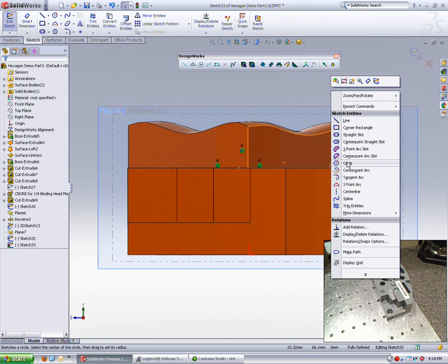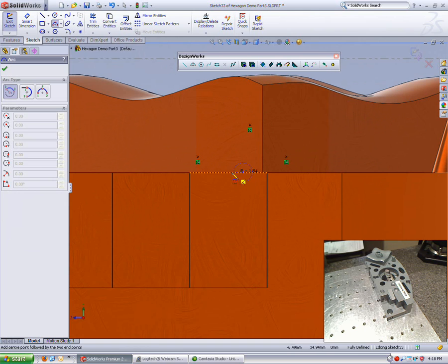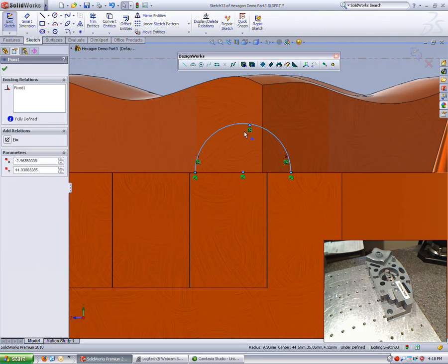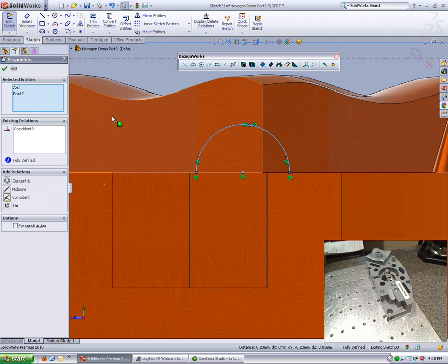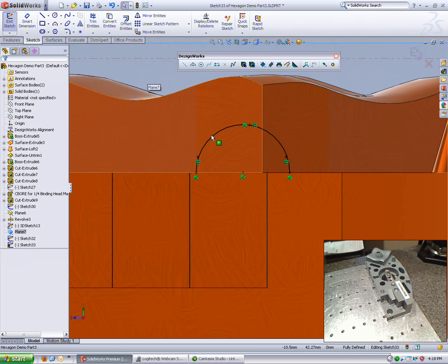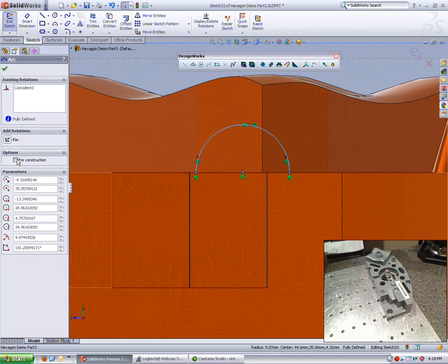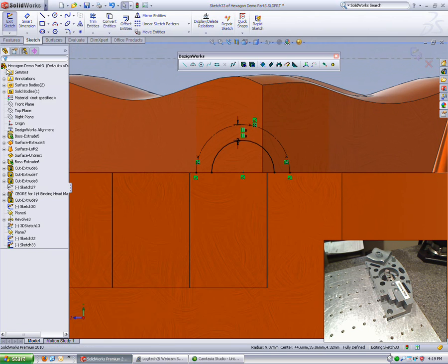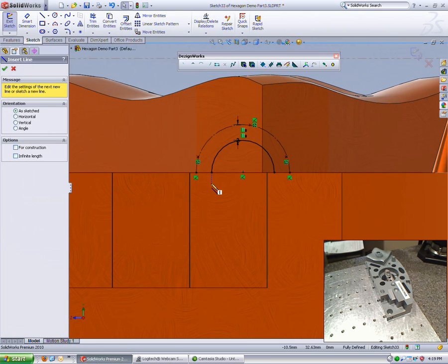Again, we may want to offset the arcs that are going to be created so that we get an accurate offset from our ball size. So here we're going to use a standard center point circle and create some relationships to those points, and then we'll go ahead and close off that profile once we offset the geometry the size of the probe.